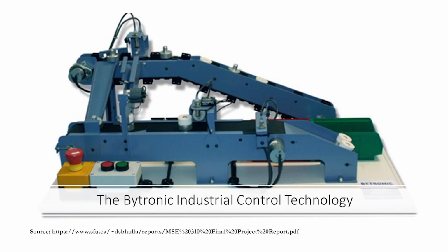Everything needs to sit on some kind of an overall base, and then once you have created these alleyways on which these go up, you need to install a belt mechanism which will need motors for it to continue going. So, you have to start thinking about what mechanisms I need, what motors do I need, what sensors do I need, what connectivity wiring do I need.